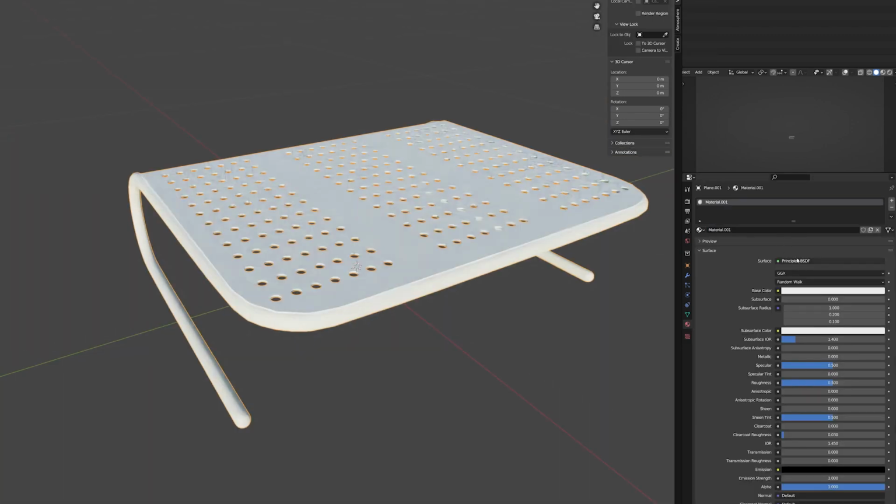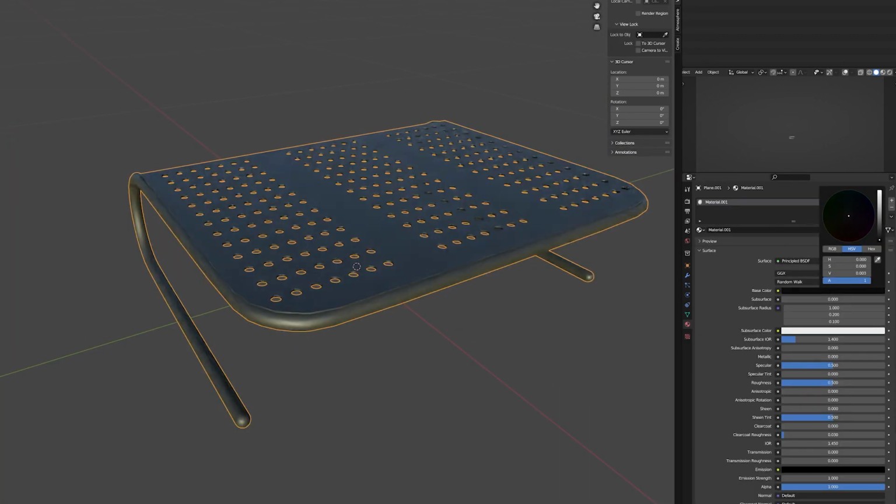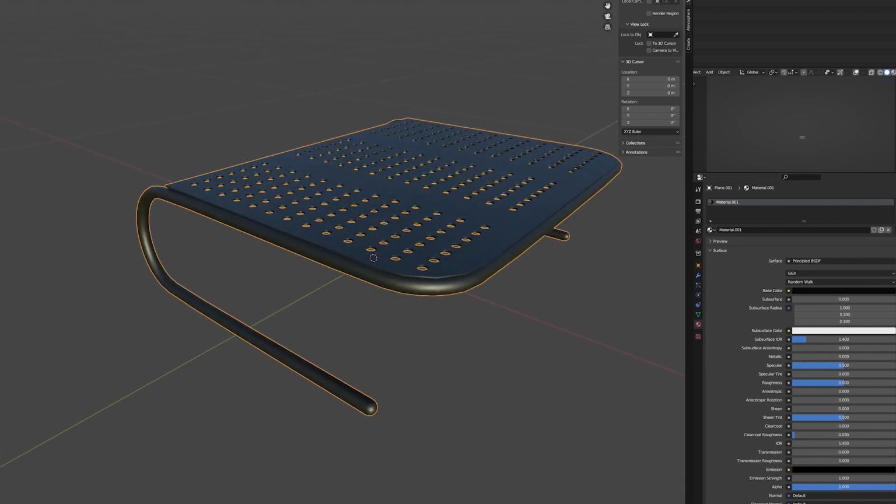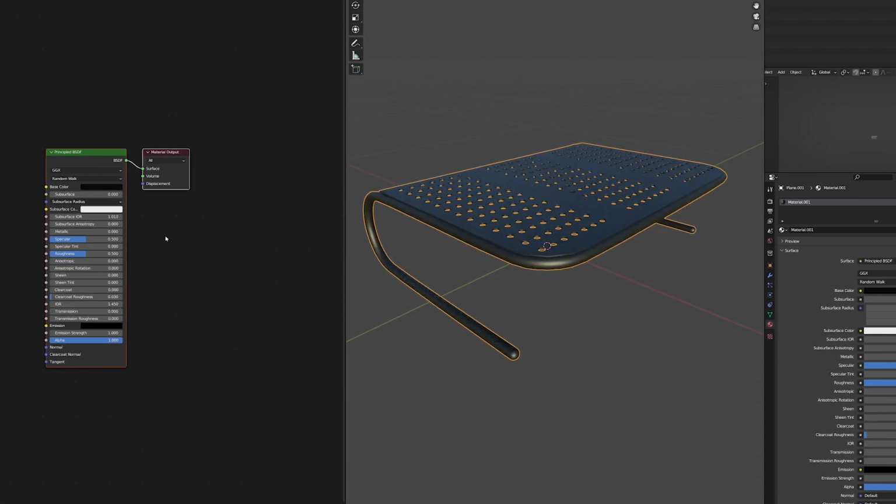So let's just enable some HDRIs here. So let's go ahead and add a simple black material to it. This really is it. I watched BlenderGuru's talk on lighting for the Blender conference, and he said do not touch the specularity slider, just leave that up at half. So ever since that talk, I've just ignored the specularity. I never mess with it.